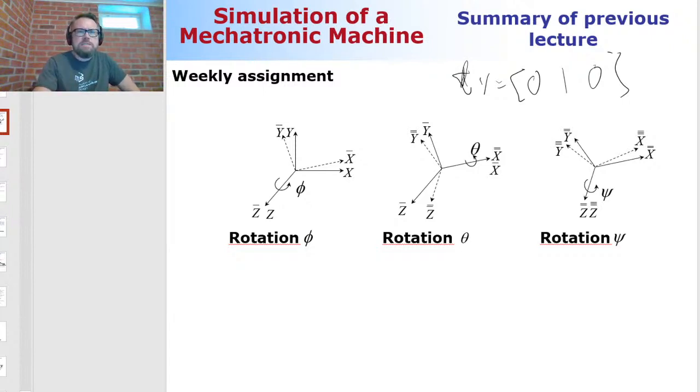And then we have a rotation sequence that is z, x, z. But there is an x here. So is it so that this sequence of rotations cannot be used to describe that rotation? Yes, it can. But we have to do a little bit of tricks to make it happen, because obviously the rotation around the y is missing.